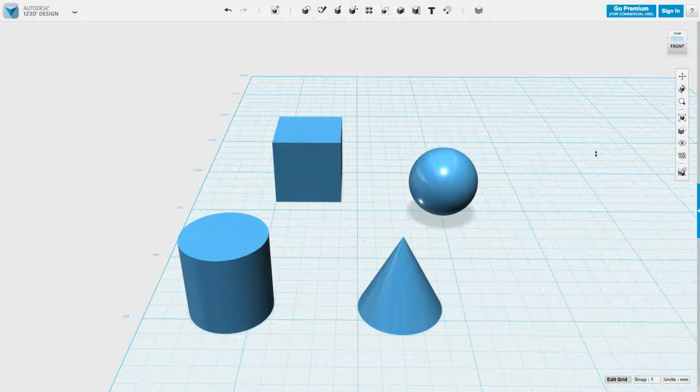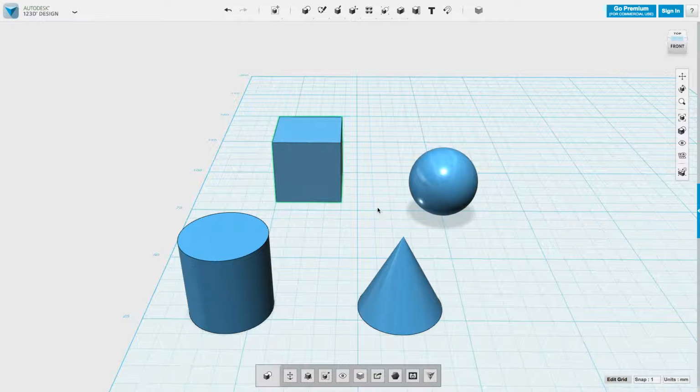Well, what you could do is, as you're compositing your 3D image, you could always change the look of something. So right now I don't have any segments on. I'm going to put my material and outline back on. I'm going to select a cube, just highlight, let go. By having the green selection over it, you can tell that it's selected. Now this button up here in the top right hand corner is the materials button.